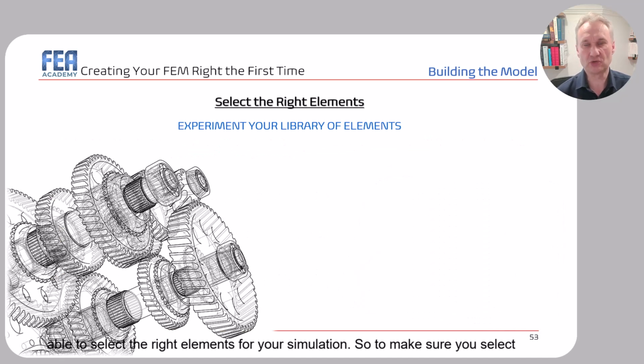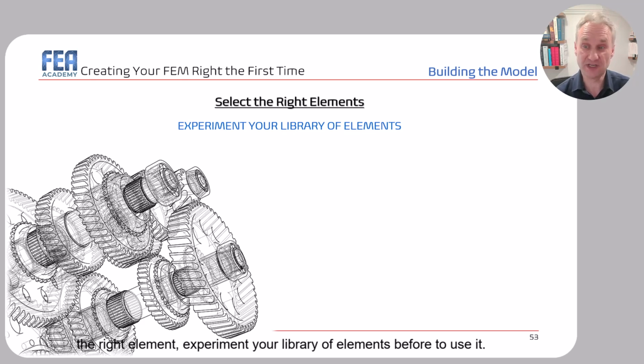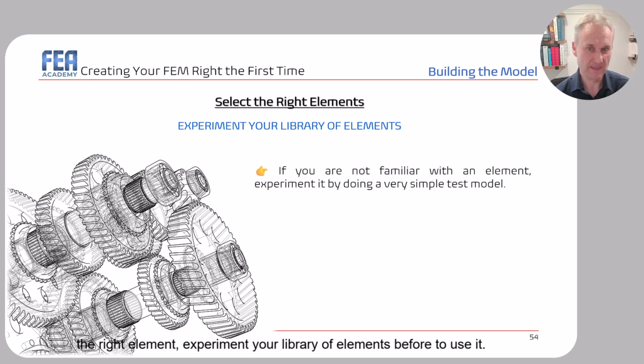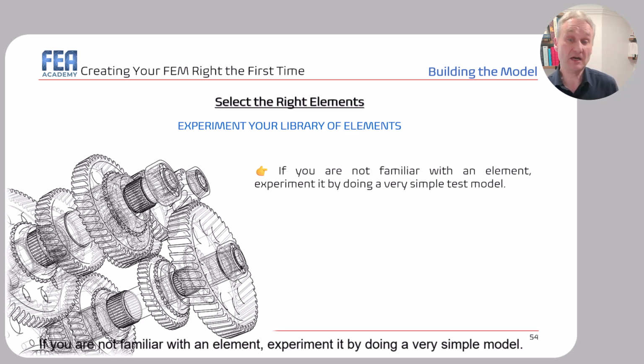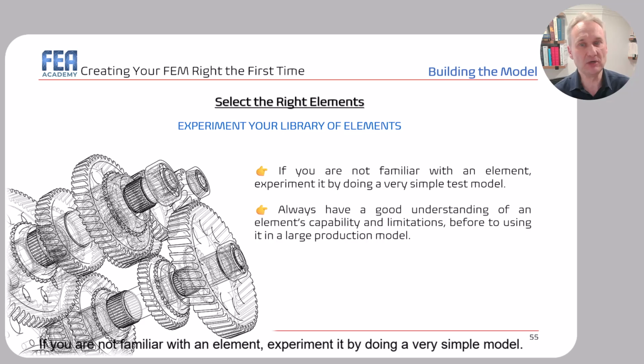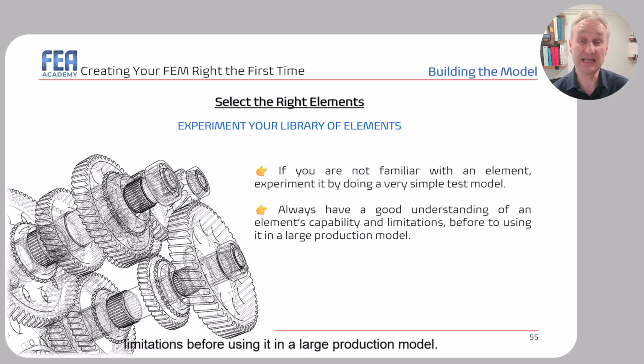So to make sure you select the right element, experiment with your library of elements before using it. If you are not familiar with an element, experiment with it by doing a very simple model. This practice will give you a better understanding of an element's capabilities and limitations before using it in a large production model.